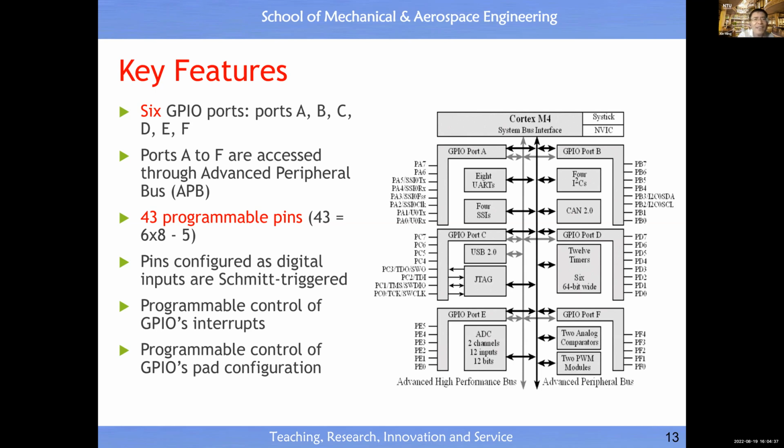You see, you have 6 ports. A port means the pins through which you can read in data from a sensor or output a control signal to your actuator. Each port corresponds to a byte. You remember in computer science and engineering, the basic unit of memory is a byte. One byte has 8 bits, and each bit corresponds to 1 pin in hardware. So for the ARM microcontroller, they give you 6 ports, each port has 8 pins. Now, in theory, you may have 48 pins.